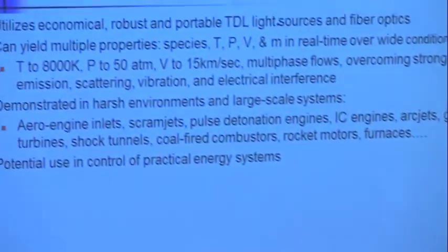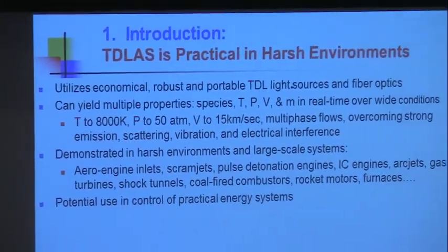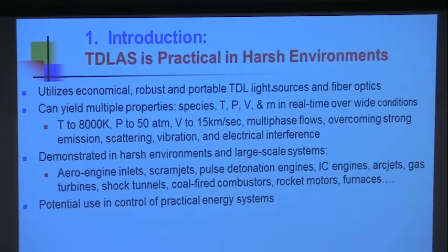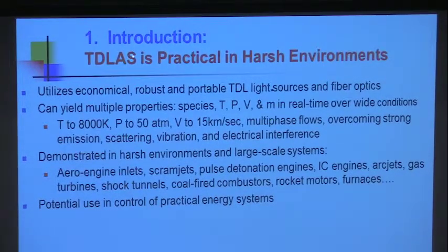So what I'm really trying to preach is that tunable diode laser absorption spectroscopy is practical, even in harsh environments. Practical because not only can we use it in the laboratory, we can take these things in suitcases and take them on the road, make use of commercially available, relatively economical, robust light sources together with fiber optics and make measurements in difficult environments remote from our laser systems.